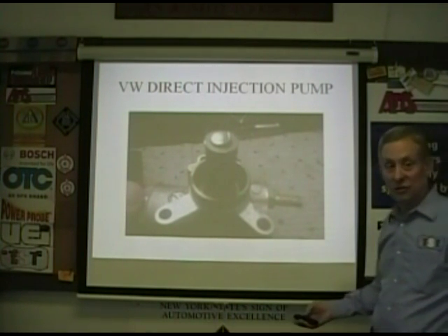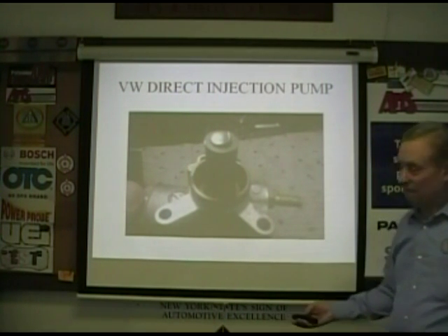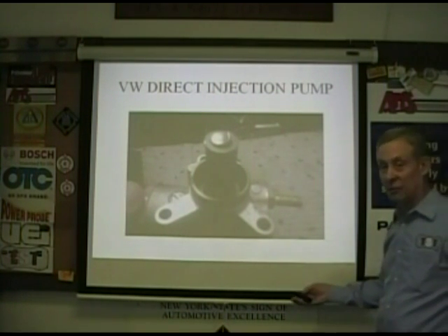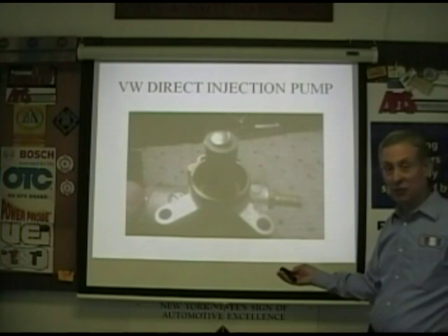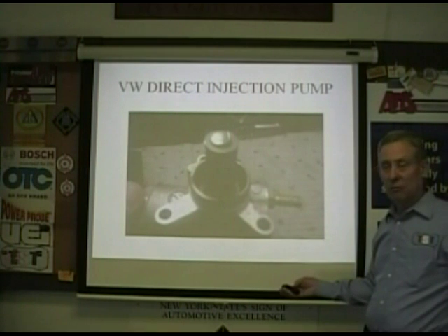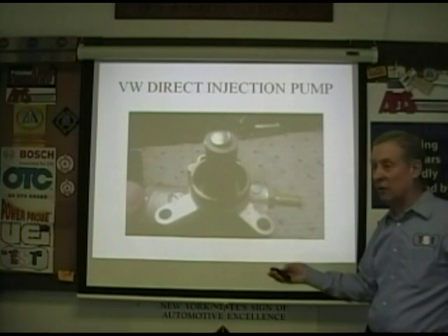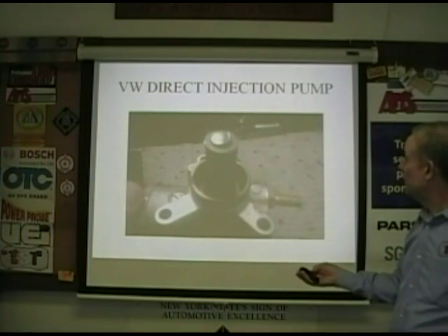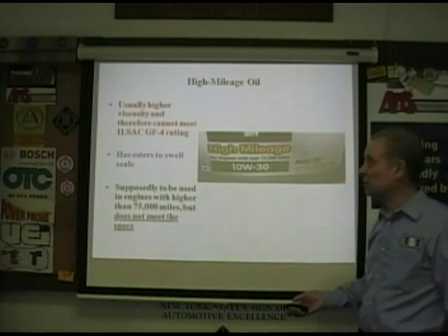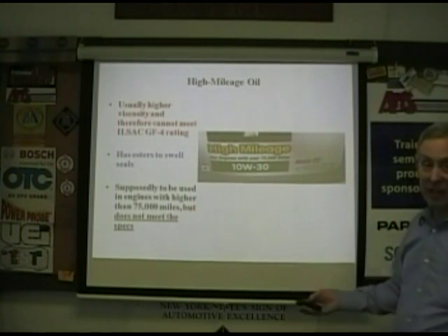So when some of our customers go to these quick places, that's where this damage actually happened. 1995 cheapy oil changes? Bad news. If it was a quick place that used the right oil, nothing wrong with that. And the right filter. But if they use the wrong oil and the wrong filter, you're taking your chances with it. So it's a must to educate your customers on that. The customer must be educated. They can't just trust. This case here was a quick oil change place that did this. And in fact, there's a lawsuit on it right now. They're going to end up buying the motor, because there was so much metal in this motor, it was everywhere. There was a lot of damage in this motor. It wasn't just a cam that got done.